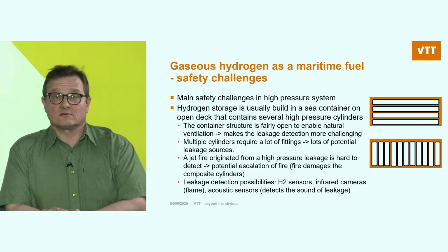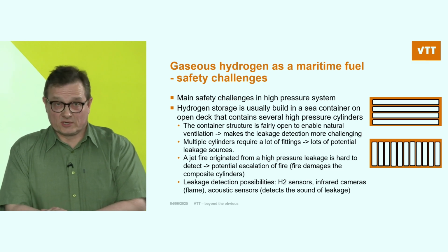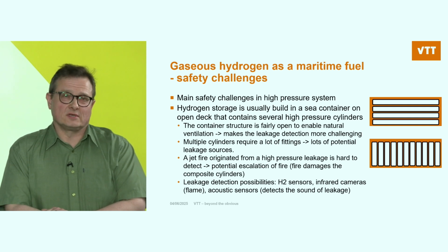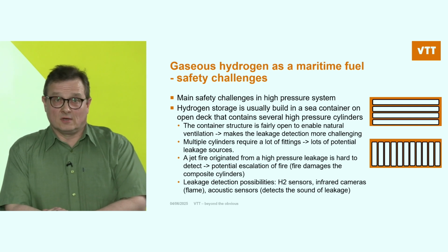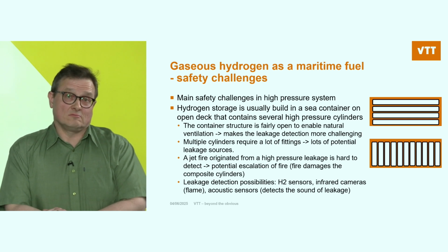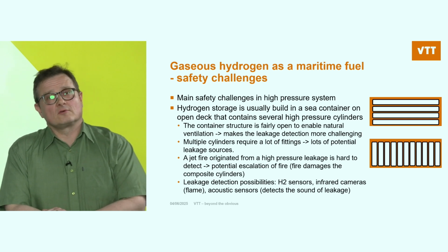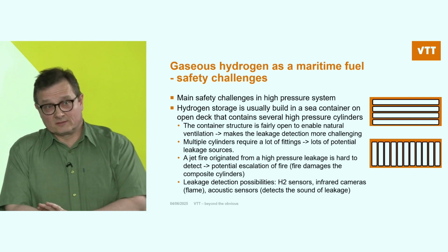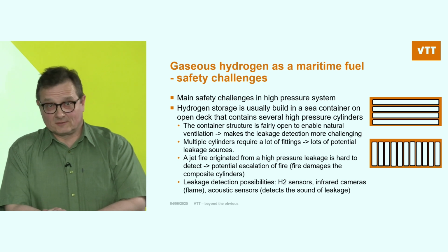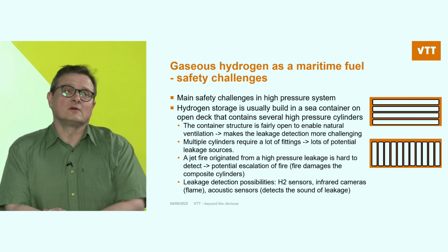Safety challenges are mainly in the high pressure system. The storages are usually built in sea containers, and they are placed on open deck, and there are lots of high pressure cylinders in the containers, either in vertical or horizontal position. And this means that there are quite a lot of fittings and lots of potential leakage sources.